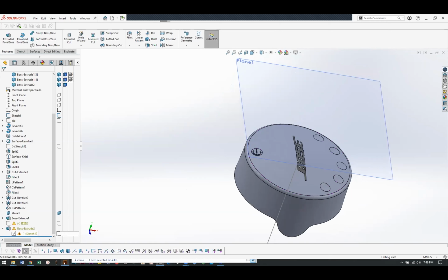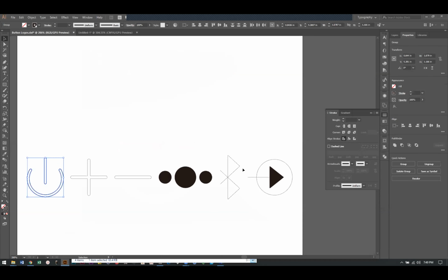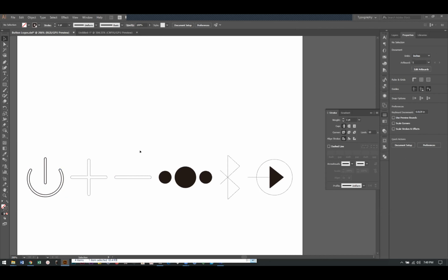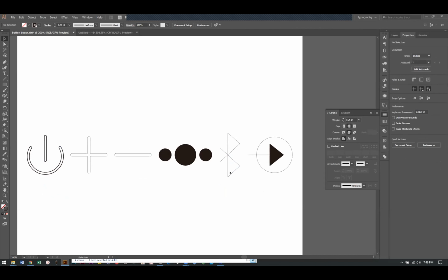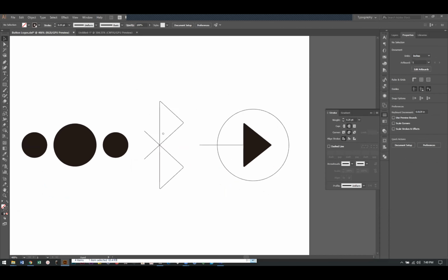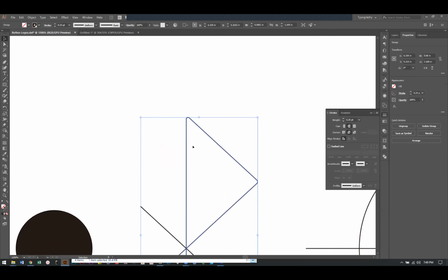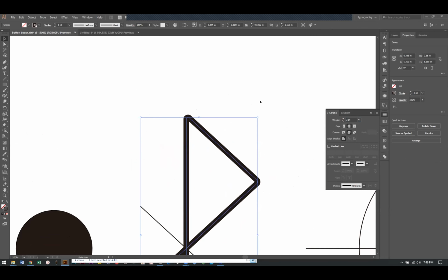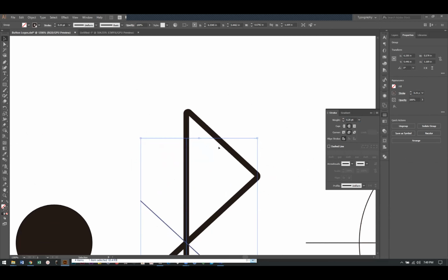One more question, since we're looking at your work here. These other graphics, have you tried to import any of those and make buttons out of them? They all failed. Really? Yeah. This one, I think would fail, the Bluetooth thing here, just because it's a straight line and it looks like your line weight is so super small. 0.25 is really, really tiny. So I think you'd probably have to bring this one up quite a bit. It's split right there.